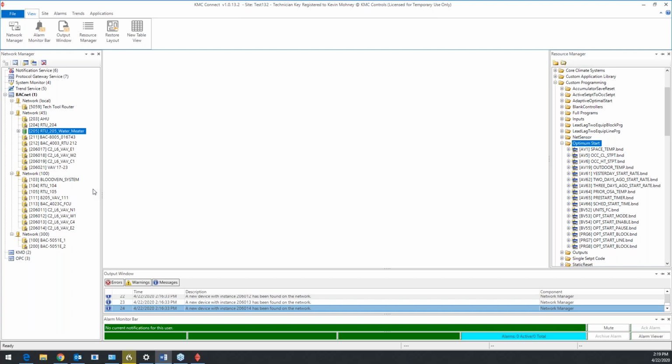I just want to touch on the standard naming again too. What that allows you to do in Control Basic is not worry about physical point locations, if you're using naming conventions in there and they're standard for you. But I think you should also use standard program usage, like off-panel points in their own program, maybe program 8 or 9. Safety programs should always be put in the same spot, like program 10 or maybe the last program that you used. I think those are all good standards too, so standard locations for different functions.